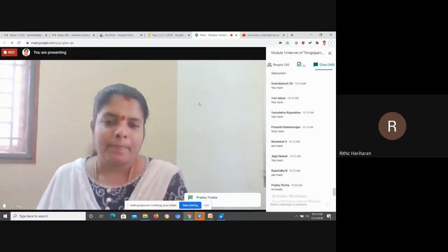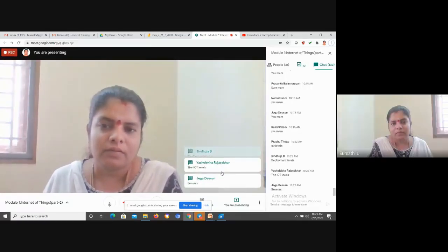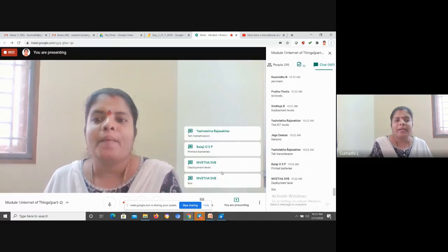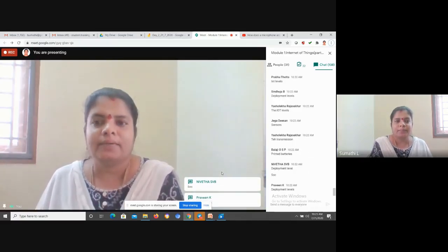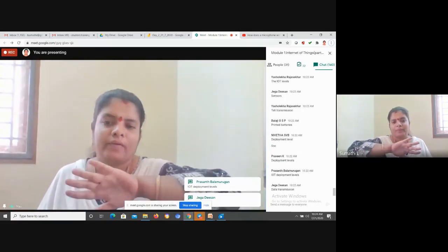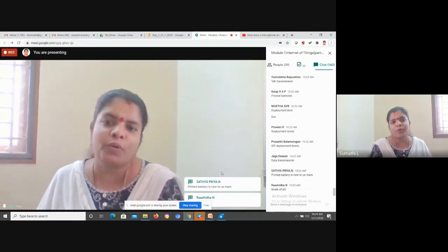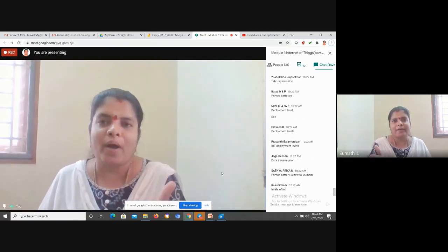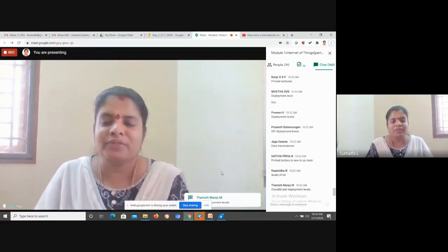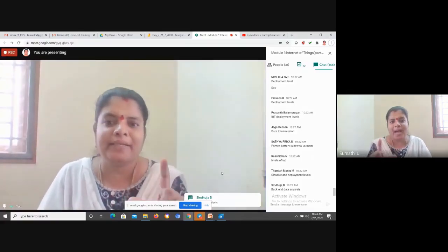Actually, I had one query. Yes. Ma'am, which is faster, the serial or the parallel mode of communication? Actually, parallel mode of communication will be faster, but due to advancement in processing, we go for serial mode, because in parallel mode you pass all the bits at a time. So it is the faster mode of communication, but nowadays we use only serial mode, because for parallel mode you need multiple wires, that is costlier, right? So you go for your serial mode. Now if you see your laptop, all your communication ports will be serial ports. Long back you had the printer parallel port.